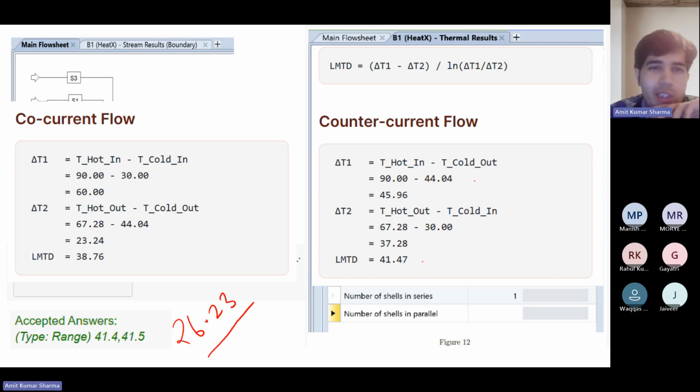Do you think it's the most efficient one? Because there are multiple heat exchangers. If we are talking about the most efficient one, it will be shell and tube type if we're considering liquids, and if we're considering a fluid like air, then fin type heat exchanger would be the best. So basically, normally we use the counter current. The most efficient is direct contact, but in direct contact, the miscibility factors come in. So technically speaking, the most efficient will always be direct contact.